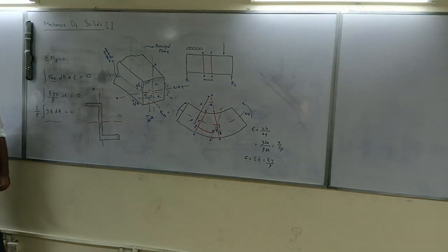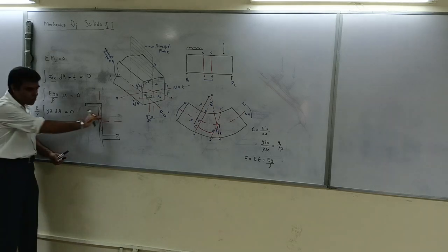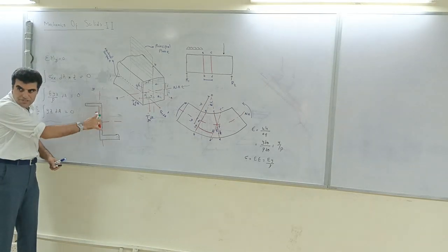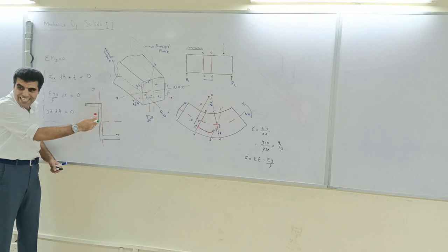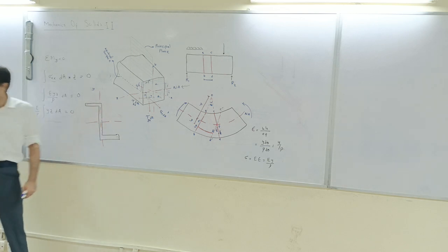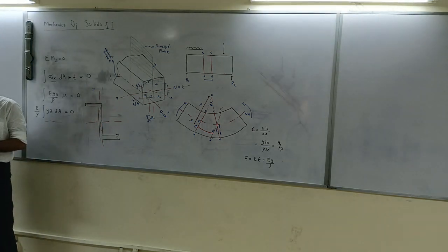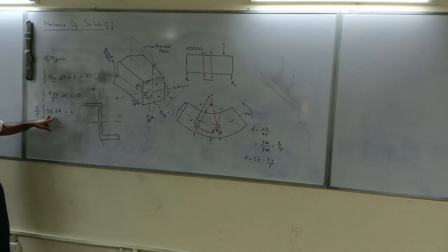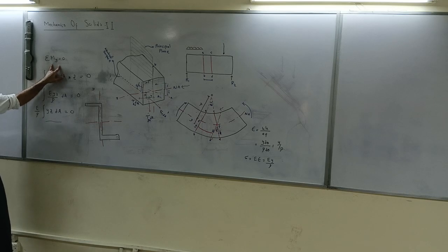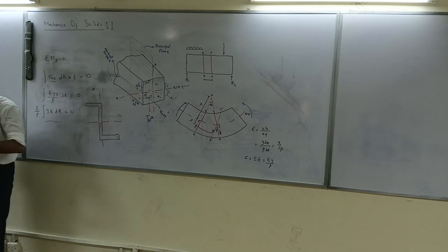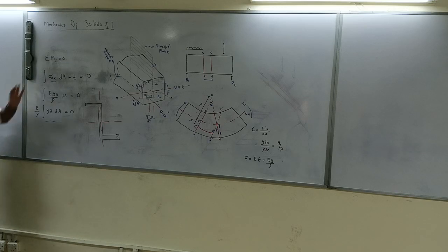Do you understand my point? Yes, sir. So therefore this will always be at an inclination. The principal axis will always be at an inclination, and you have to make sure that you apply the load on the principal axis. If you don't, this won't be zero. So this will start rotating about the y-axis. Are you getting the concept? Yes, sir.